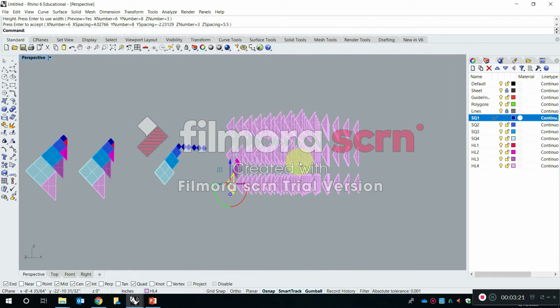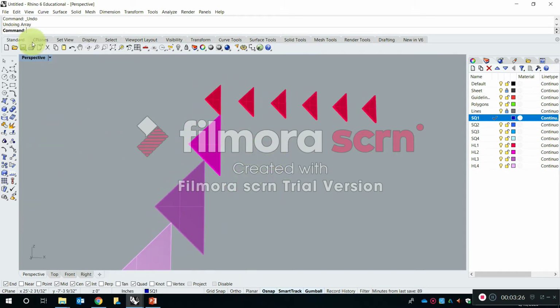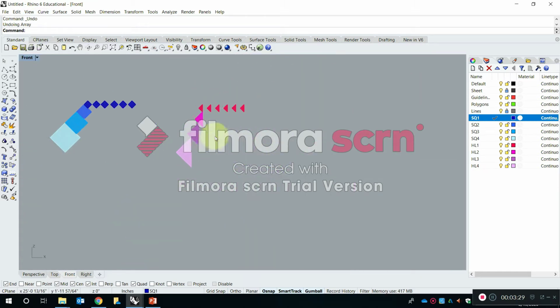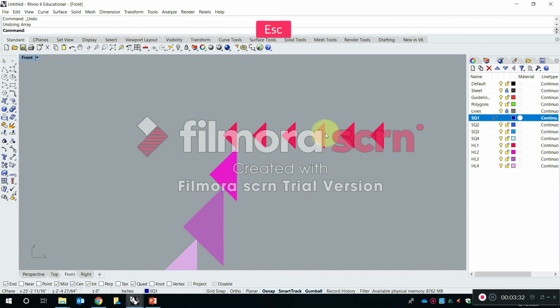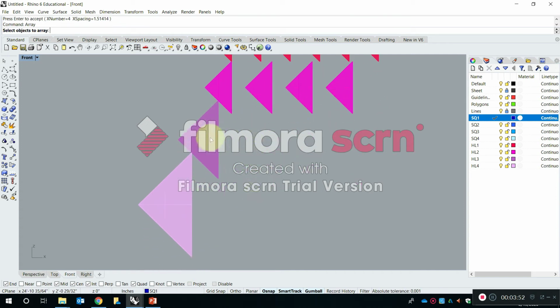Right? No, there's more than that. Okay. So whether you use array or copy, that's up to you. Let's keep doing array just for practice, right? So we'll do this right there. How many of these were? 4, right? So now in the y, I just want 1, and the z, I just want 1, right? And I start doing my spacing right there. Right click, and this one is how many? 2, right? And for 2, it's the same if I just type copy.